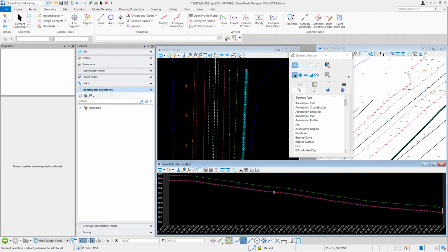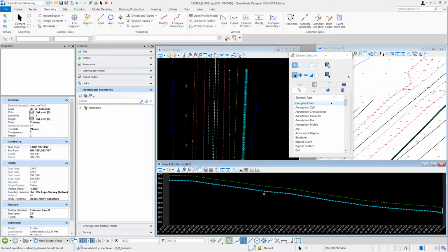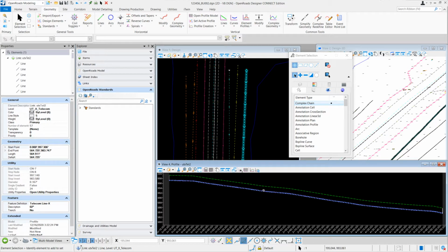All right. But what if you want to maintain some of the existing and just change certain parts of it? So here's what I'm going to show you guys. It's just a bunch of clicks here. If we select that profile, there's a tool here that says convert to profile rule. So we're going to convert it to a profile rule, right? Now that it's a profile rule, we're going to come here and create a best fit profile.